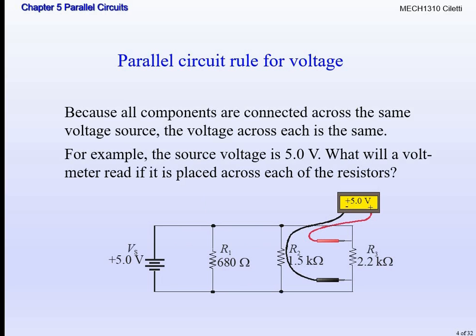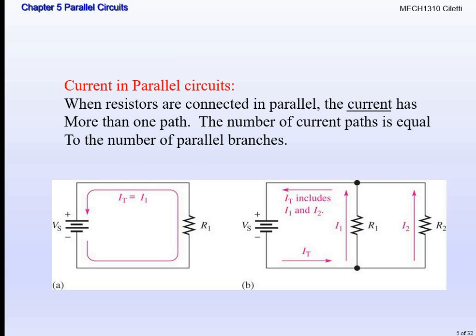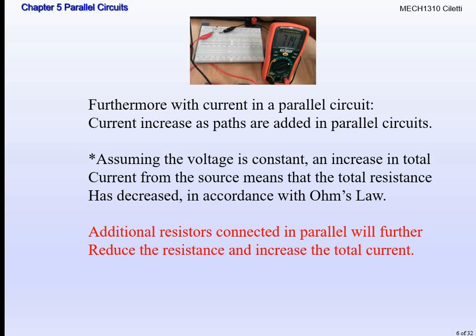All right, so when we're talking parallel circuits, current has multiple paths. More than one path, and please remember, we can call them paths, or we really call them branches, so we can interchange both of those. Whereas in a series circuit, like the one on the left here, there was one path for current, and then we had voltage drops. In a parallel circuit, the voltage remains the same, and we have different currents, or multiple paths for current. It's really kind of breaking it down when we take a look at the two. So always assume that the voltage is going to be constant there.